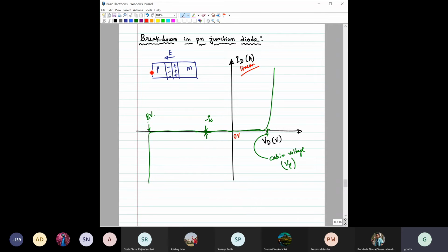Now when you have reverse bias, you have applied additional biasing. As a result, an external voltage has been applied, and we know that it will be in the same direction as this built-in electric field, VBI. So the overall electric field is the combination of these two. And from our earlier discussion, you know that these two silicon regions side by side are bonded with covalent bonds.